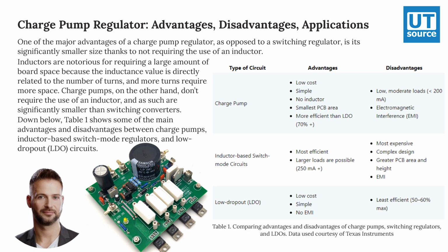Charge pumps, on the other hand, don't require the use of an inductor, and as such are significantly smaller than switching converters. Down below, Table 1 shows some of the main advantages and disadvantages between charge pumps, inductor-based switch mode regulators, and low dropout, LDO, circuits.